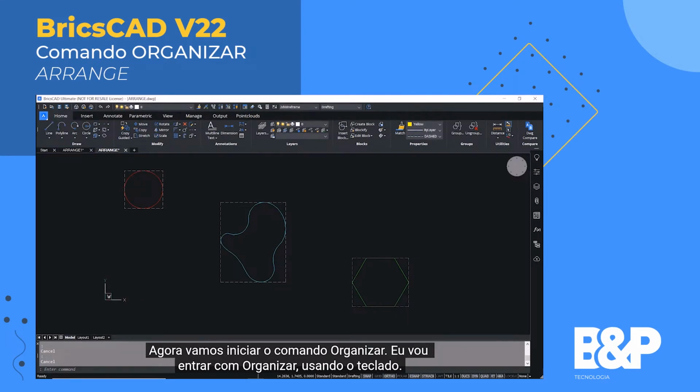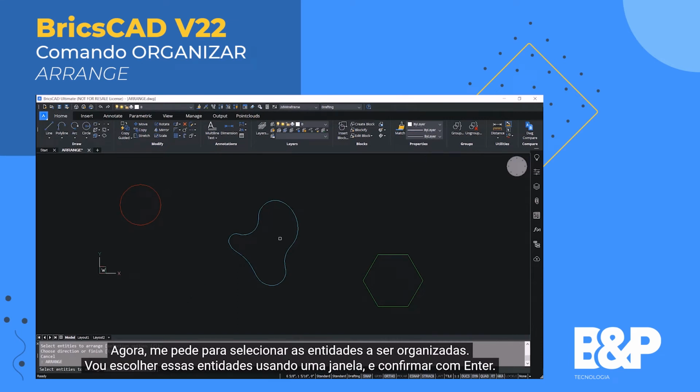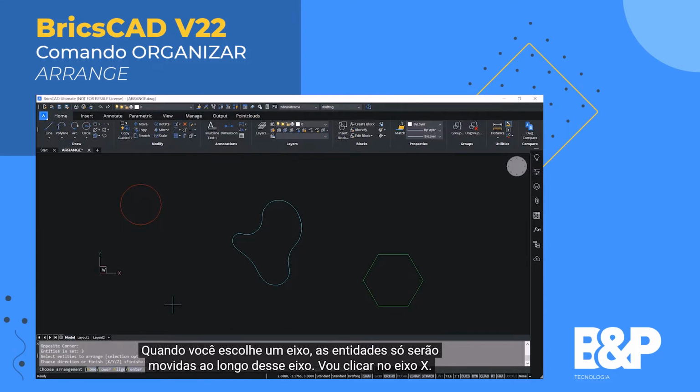Now let's launch the arrange command. I'll input arrange using the keyboard. Now I'm asked to select the entities to arrange. I'll choose these entities using a window. Give an enter. Next, you have to choose a direction which is specified using X, Y, and Z axis of the UCS. When you choose an axis, the entities will only be moved along this axis. I'll click on X axis.